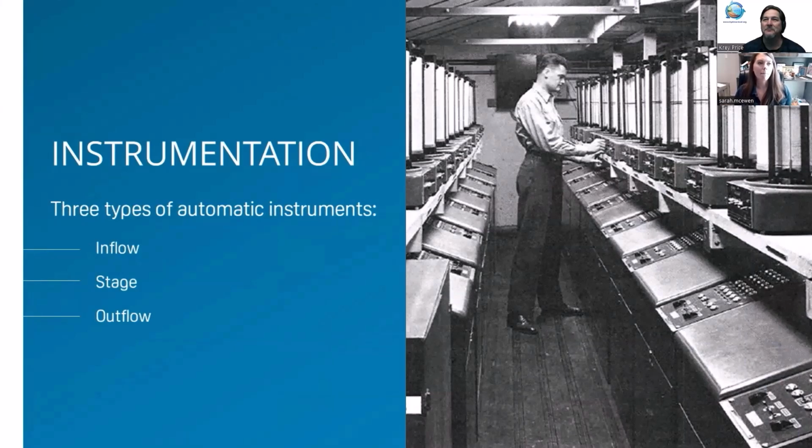How are you going to model and control 60 acres of concrete and run these different simulations on this massive scale? Initially, it was thought that it would take 30 to 40 people to run this model, pulling on the levers and everything to get it to go. But they used player piano technology and automation to run historic hydrographs through these different inflow controllers. There's 70 to 80 inflow controllers throughout the system that would pull water based on the player piano hole punch technology, ramp up the hydrograph, run it through a V-notch weir, and push out the flow to match those gauged beds.